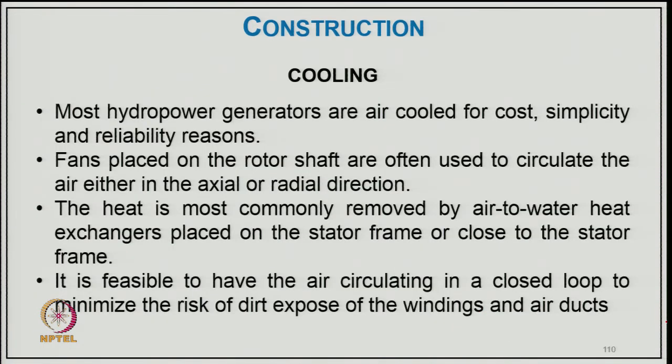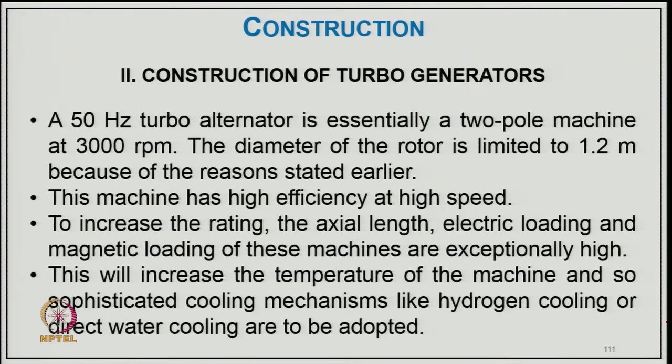Now coming to the cooling, most hydro generators are air cooled for cost, simplicity and reliability reasons, and fans placed on the rotor shaft are often used to circulate the air either in axial or radial direction. The heat is mostly removed by an air to water heat exchanger placed on the stator frame or close to the stator frame, and it is feasible to have the air circulating in a closed loop to minimize the risk of dirt exposure on the winding and air duct.